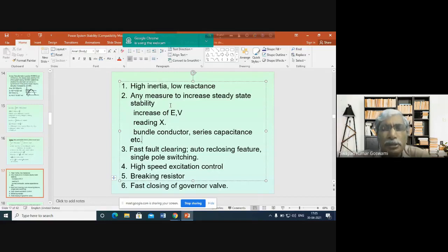This is a very problematic situation. Why is this a very problematic situation? Because when we use a protection system for a transmission line, we set our protective devices depending upon the fault current. If the current is less, we assume that the fault is far away from the generator. If the current is higher, the fault is closer to the generator. But this concept will be proven false if you connect a capacitor in series with the transmission line.